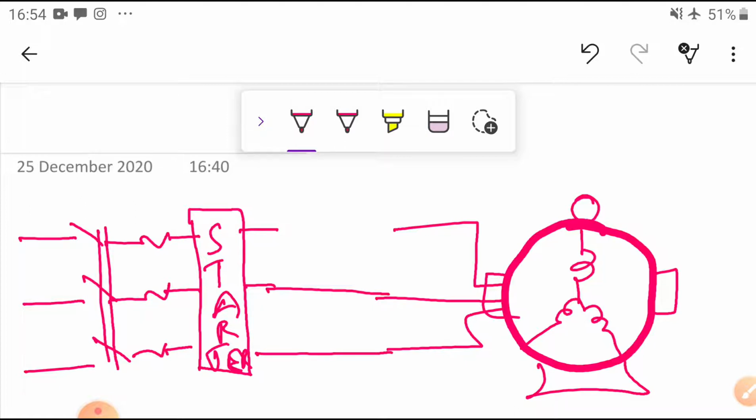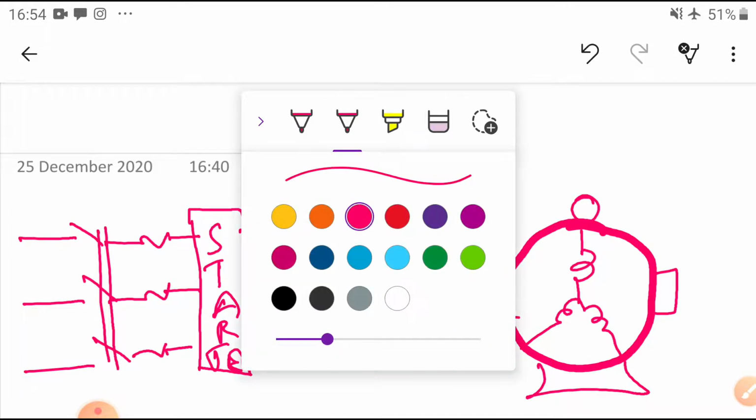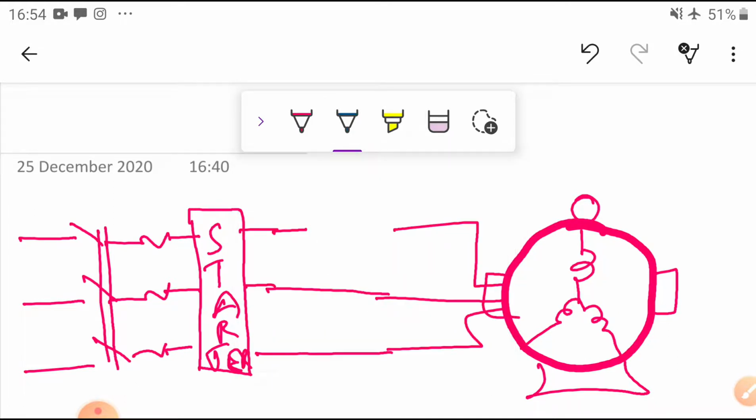Now I want to know the power, so I can connect here the CC coil of the wattmeter. So what is a wattmeter? A wattmeter has two coils. One is the CC coil, another is the PC coil. Okay, these are the 4 terminals of the coils.